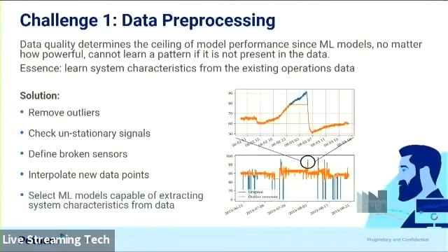We need to do data processing, eliminate peaks, right? We need to eliminate areas of downtime, places of lack of stability, find when we have broken sensors, all of that. But at the same time, we don't want to filter too much so that we lose the data, right? So it's a little bit of an art there. But you just have to create the right pipeline to do that filtering, smoothing, alignment. Process data historians typically have different resolutions for different variables, so all of these things have to happen.